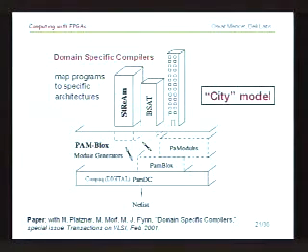So once we know that we are targeting a stream architecture, we can write a compiler that targets this particular architecture, which is a stream architecture, and knows how to do the equivalent of register allocation or scheduling for this particular architecture. So you have an infrastructure below that is basically the module generation environment, and you can target that module generation environment with a set of different compilers that are each specialized to a particular architecture.